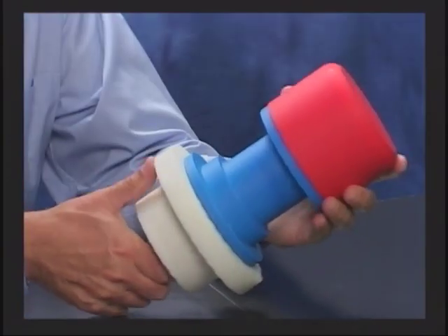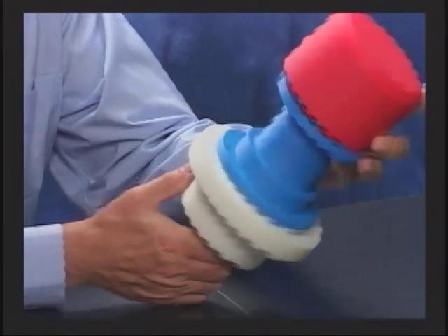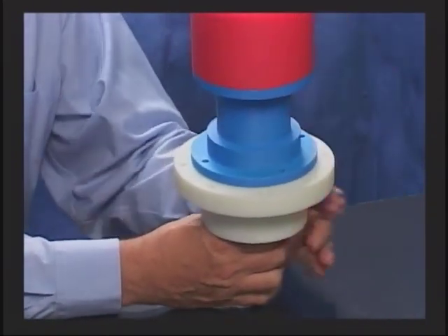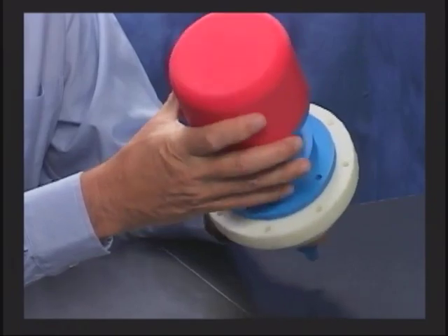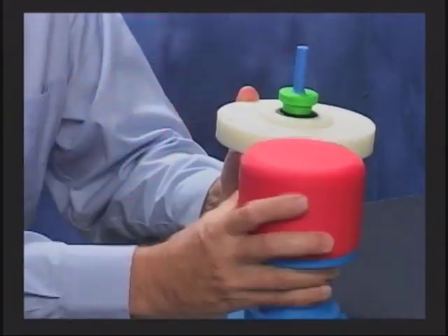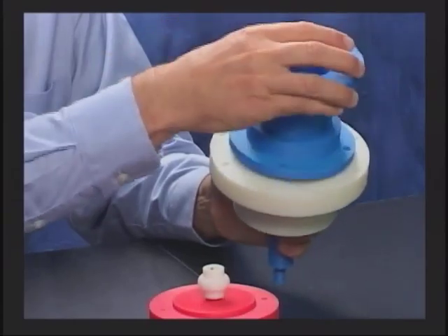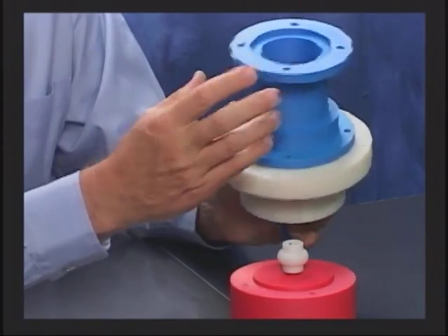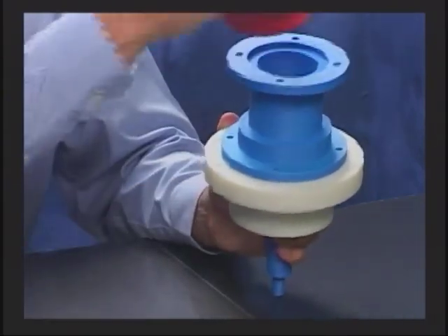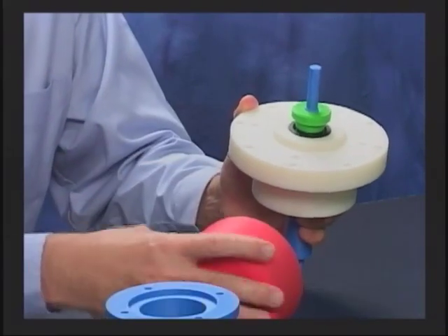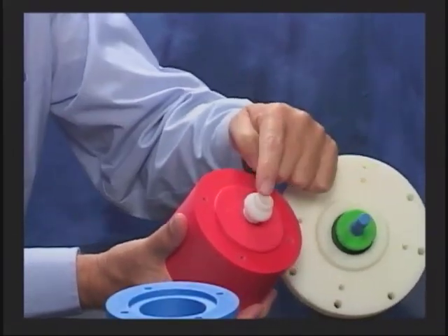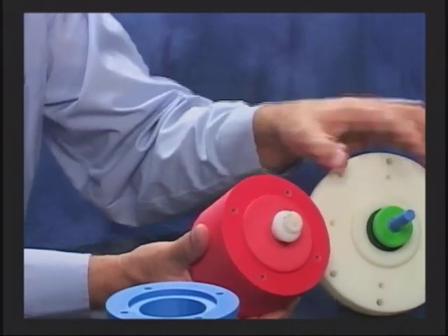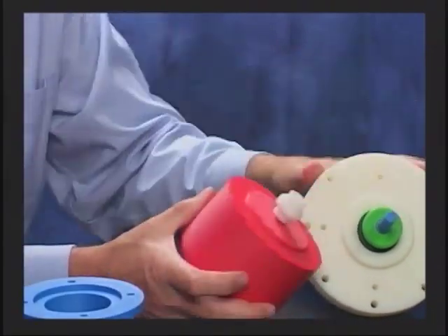Remember a little while ago when we were looking at the stack problem we had, let's take a look at our model here, our mixer. Remember what we did with just a linear stack. In the linear stack on this mixer, we had all of these different pieces going together. Here's our adapter, and we had the coupling matching up with the shaft here. The initial calculations we did were just to find the relationship between this diameter of our coupling and the shaft when they went together.